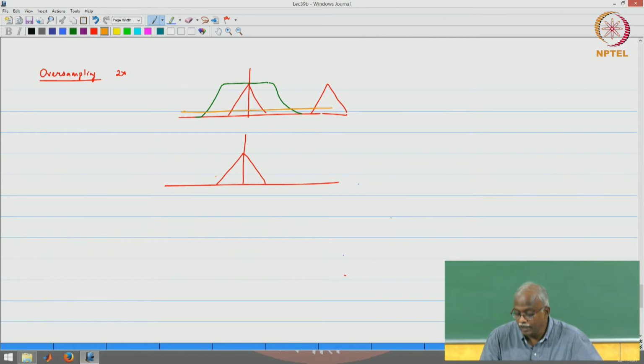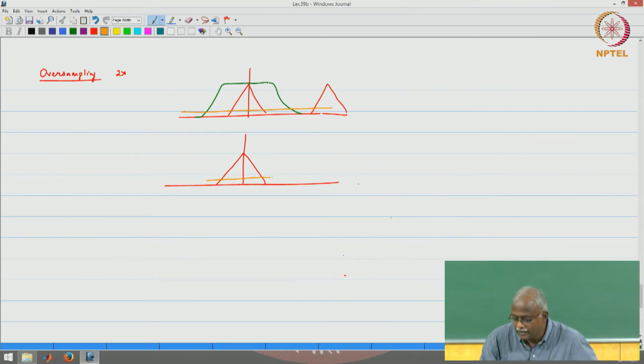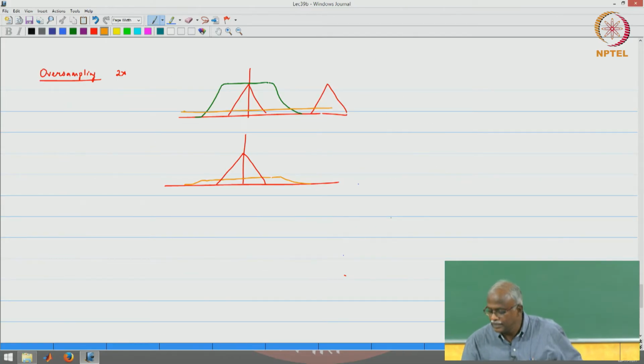There is quantization noise in the desired signal band, and of course outside of it also, because the anti-aliasing filter did not kill all those samples. Basically you will see some kind of roll off of the quantization noise. So the noise is present even outside of the signal spectrum.